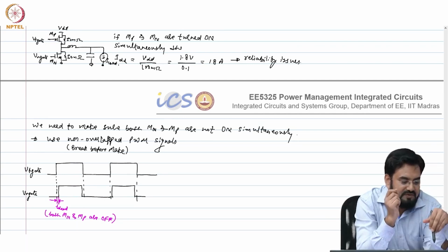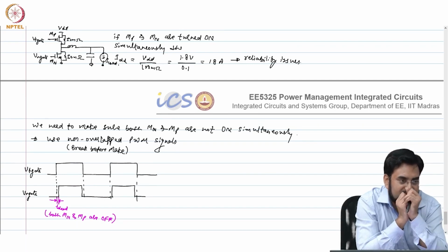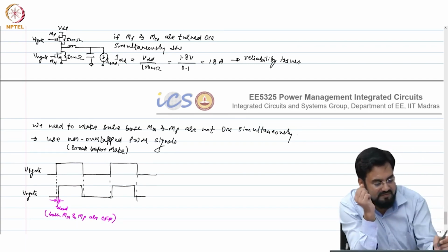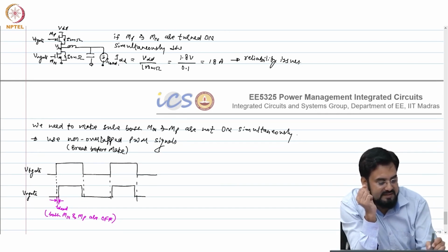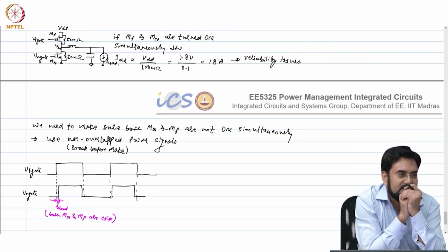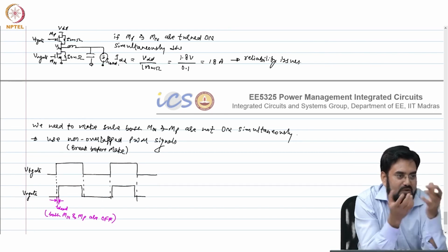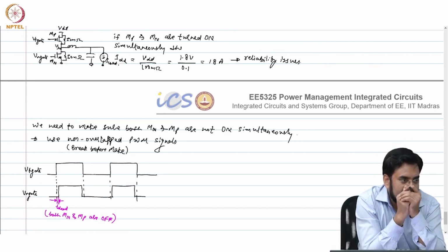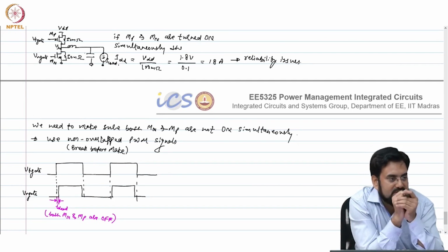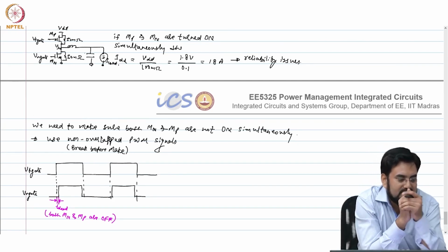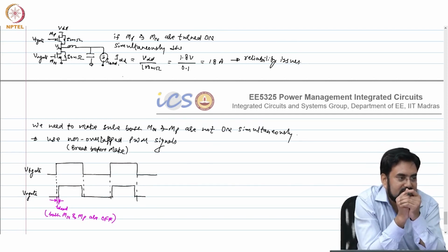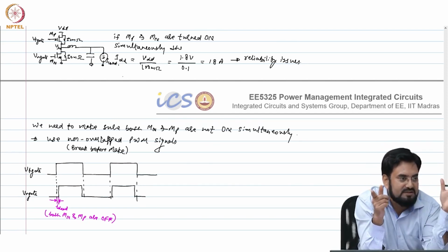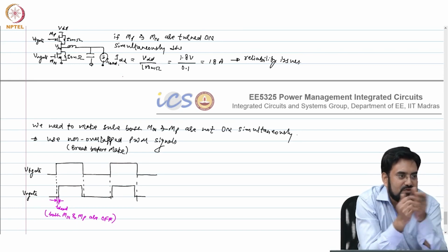So it will rise and fall based on the voltage. So if you leave that high impedance, the other node of your, or VSW, if I call it VSW, and the current is still flowing into this. I mean, load current is, let's say, 1 amp, which was flowing through NMOS, and you turned it off. You leave it high Z. That 1 amp will keep flowing for a certain time, unless the voltage across the inductor falls to zero.